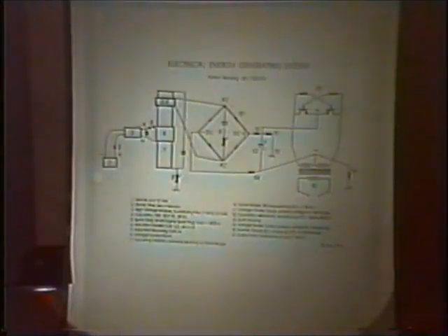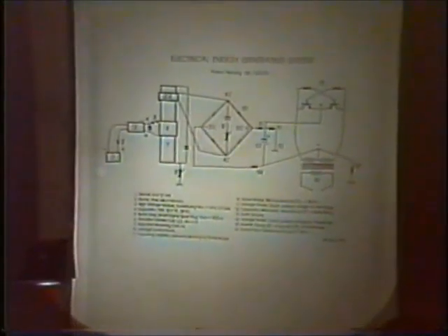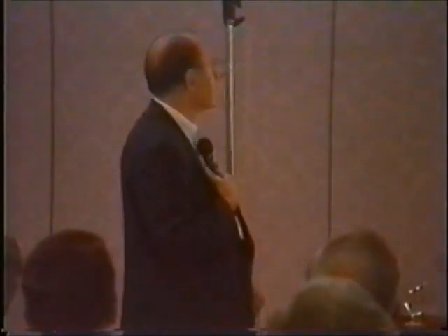This device, as you did it there, what's the duty? Duty cycle. Can that run continuously? Oh yeah, there's no moving parts there to wear out, and you're not dissipating power anywhere in substantial quantity. The only thing I'd be concerned with would be 11 and 14, those voltage dividers. That's going to be tricky because, like I was saying a while ago, the resistors aren't necessarily just resistors.